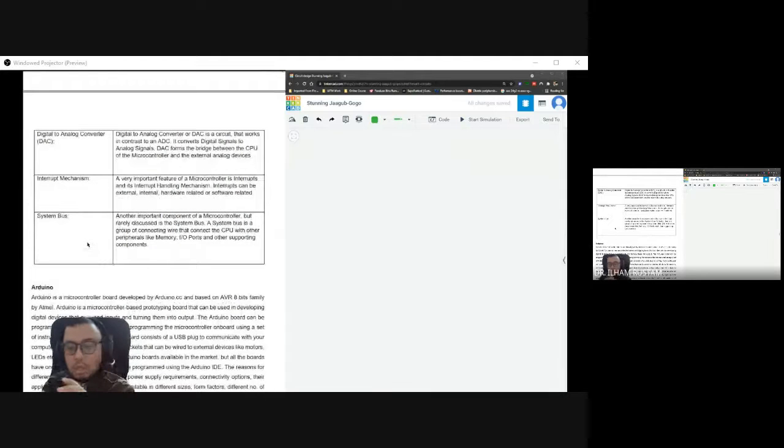And then the interrupt machine, let's say for example you make a menu display, so as long as the user doesn't press anything on the menu, the menu will keep on displaying on the LCD. If you press, like an ATM, you press how much money you want to withdraw, what you press starts the interrupt, so it will bring you to another place, another menu for example, or issue a special instruction based on what you pressed.